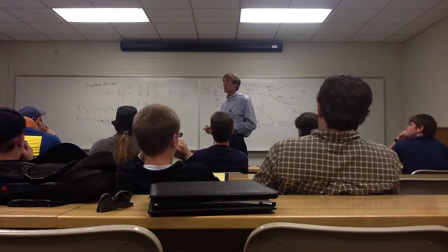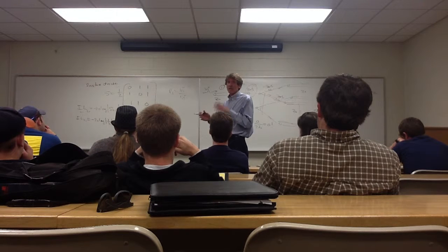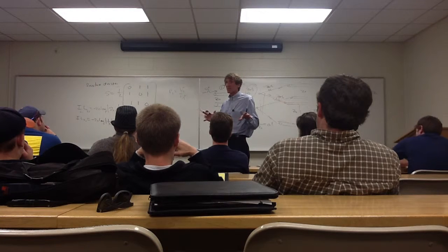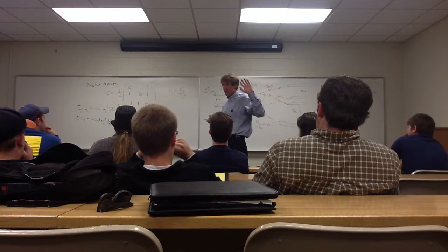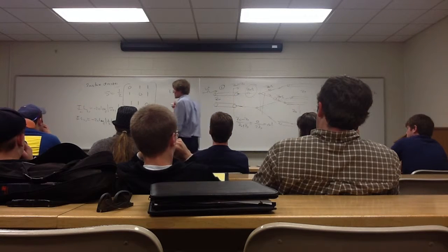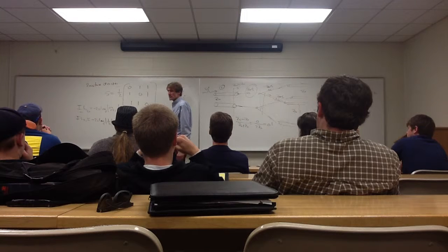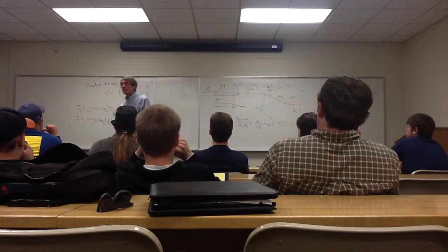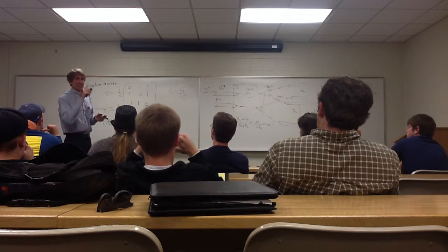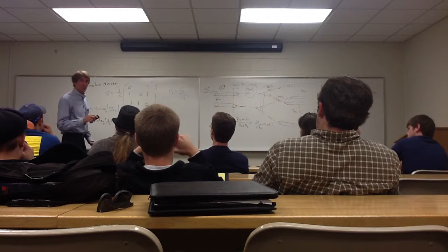That's how come this type of divider is something you use if you've got plenty of signal and you don't need to worry about the signal being reduced any further down the circuit. This would be something you could do. And it's very inexpensive, there's no phase problems. Really easy thing to do. That's 6 dB. But we can do better than that. We can actually get it down to only 3 dB loss for a Wilkinson divider.